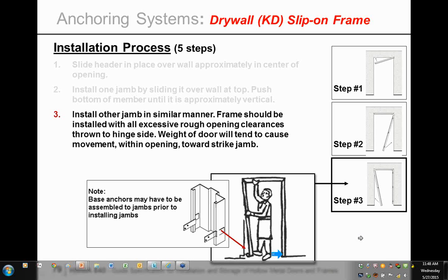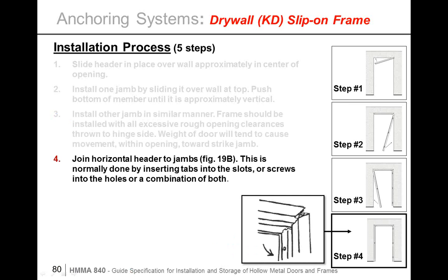Now, the only other way that I can think of that would be applicable, some manufacturers offer really focused, dedicated frame construction where it's not a drywall slip-on frame construction, but they would screw through the face of the frame at designated locations right into the wall construction. With that, you would have exposed screws setting inside some type of dimple. That's what I would see as the variations of how dimpled frames would relate to anchors. Hopefully that answered the question, Hannah.